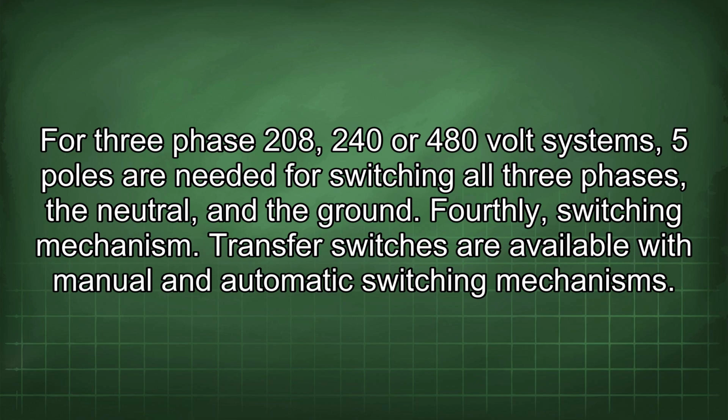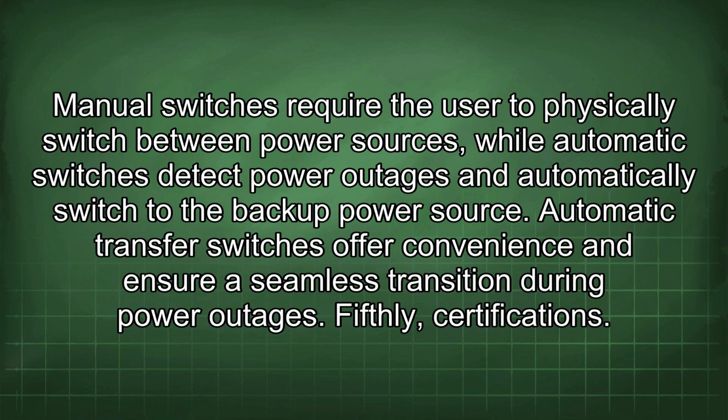Transfer switches are available with manual and automatic switching mechanisms. Manual switches require the user to physically switch between power sources, while automatic switches detect power outages and automatically switch to the backup power source. Automatic transfer switches offer convenience and ensure a seamless transition during power outages.